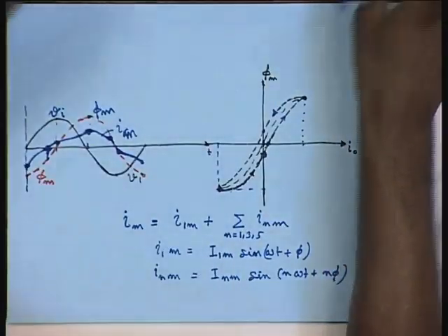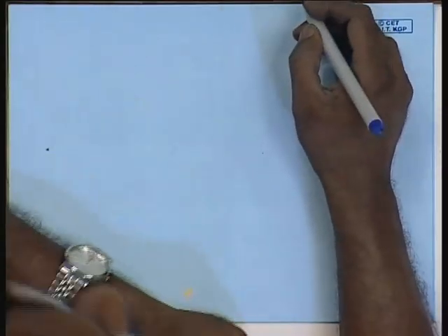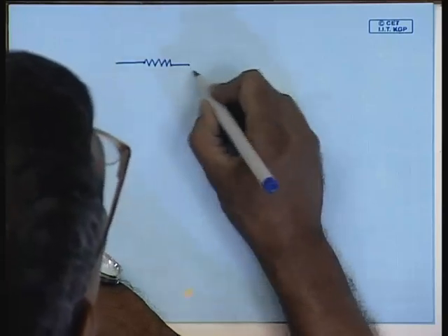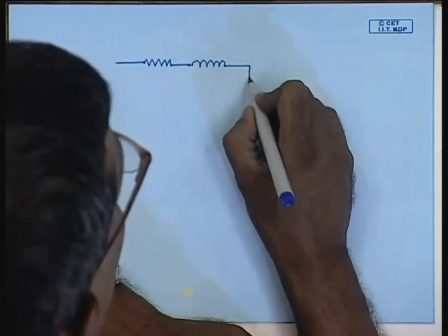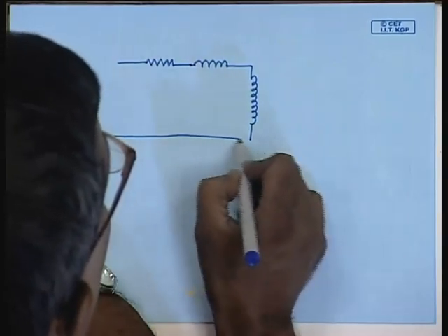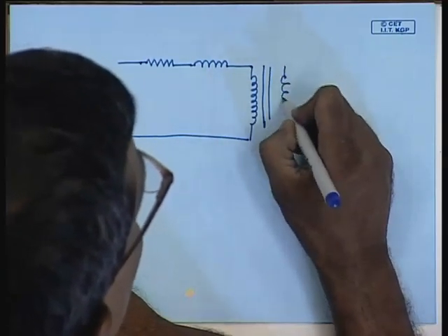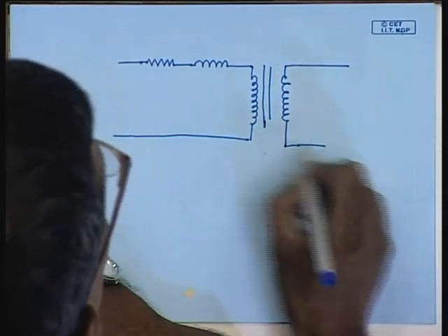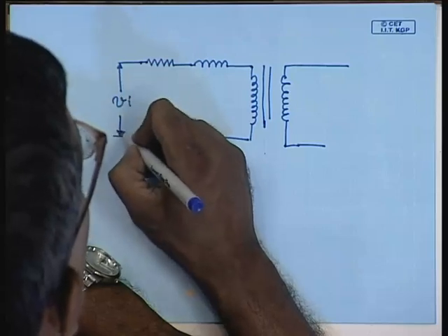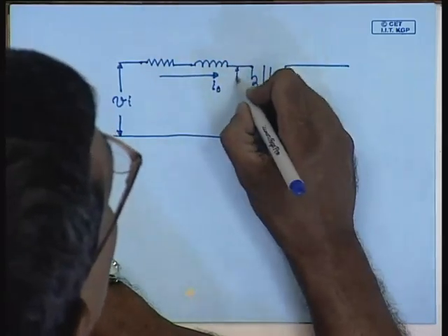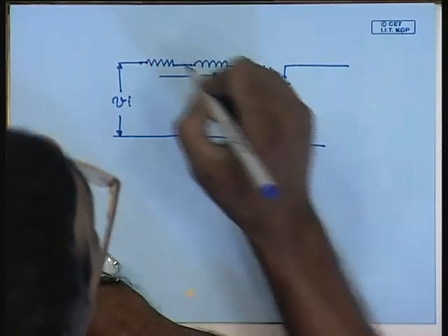However, since the magnetization current is non-sinusoidal, one would expect, if one assumes the winding resistance, that the applied voltage is a sine wave, the current drawn I0 has harmonics, then one should expect the induced voltage E also to have harmonics.